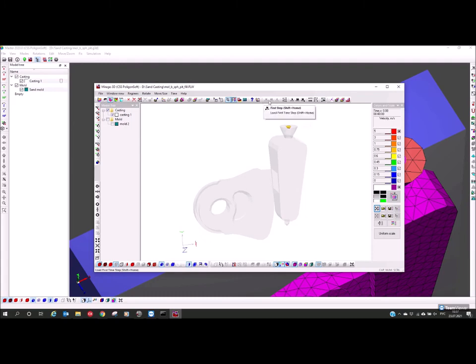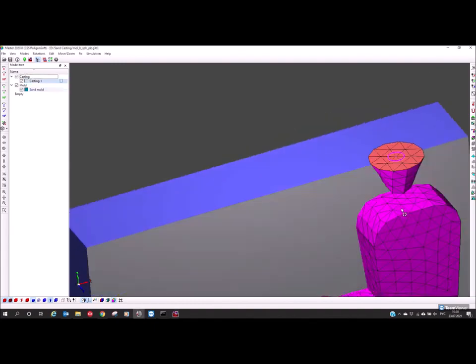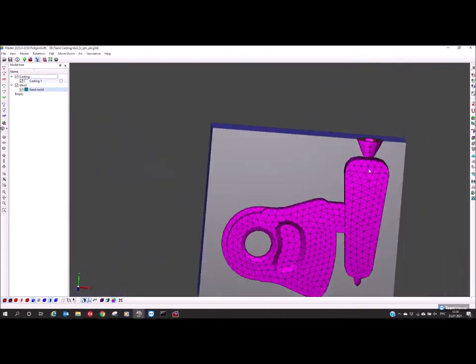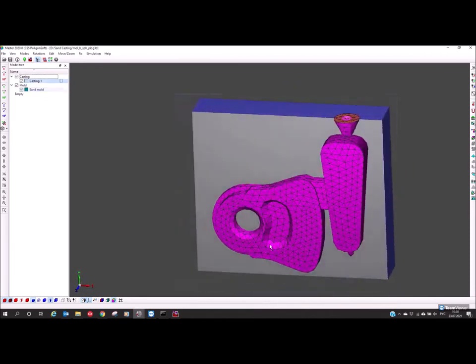And here's a player toolbar, and I can press this button to move next step or move a few steps, and as default it's 5 steps forward, and to move to the last step, so you can see how it looks. We don't see a stream here, and this is a visualization error because our finite element mesh is too big.